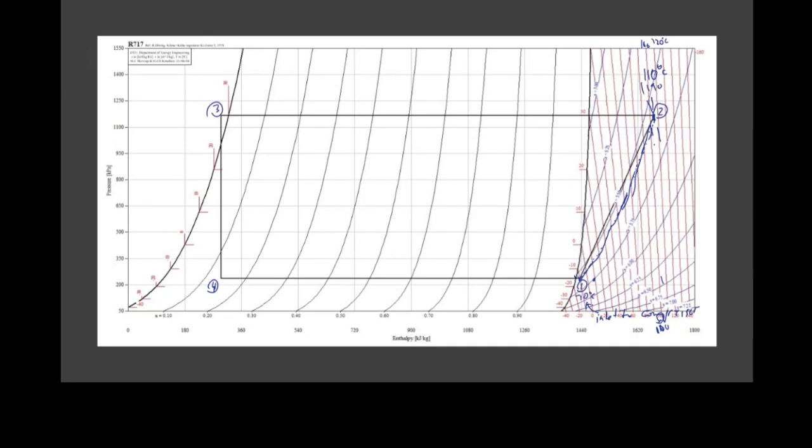And the other thing is, ammonia gets really hot when you compress it. It's one of the thermodynamic characteristics of this particular refrigerant. It's different for different refrigerants, but ammonia is going to be stinking hot. This makes it hard on the compressor, on the lube oil, on the valve plate assembly and things like that. When we look into more detail about the compressors, we'll see that a high discharge temperature cutoff is fairly common on ammonia compressors. If it gets to, say, 130 degrees Celsius, the machine will trip off.